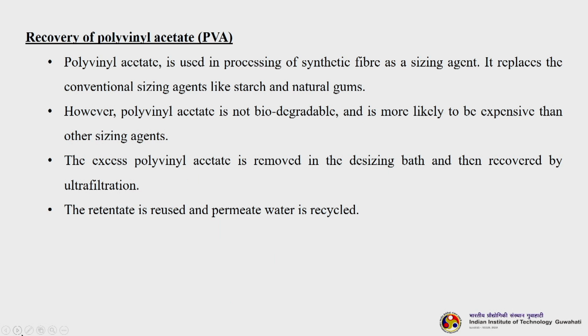Another application is the recovery of polyvinyl alcohol, PVA. Now, you know PVA is used in processing of synthetic fiber as a sizing agent in textile manufacturing industries. So, it replaces the conventional sizing agents such as starch and natural gums. However, PVA is not biodegradable, hence it is more likely to be expensive than other sizing agents. The excess PVA is removed in the desizing bath and then recovered by ultrafiltration. The retentate is reused and permeate water is recycled.